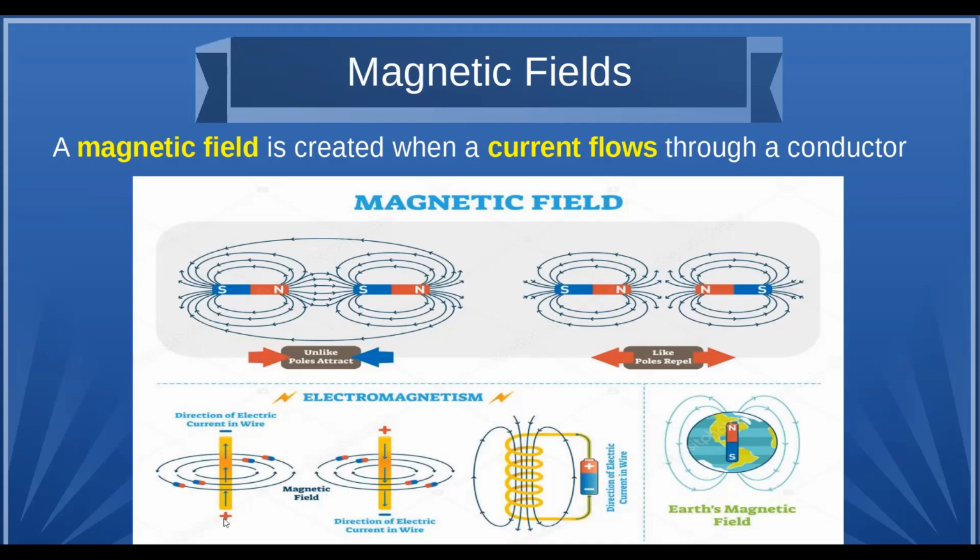So in this one, we're showing a conductor with the current going in that direction, and use the right-hand rule. Okay, your thumb is the direction of the current. Your fingers are the direction of the magnetic lines of force. That's kind of arbitrary, somebody decided at some point in time. So they're circulating in the counterclockwise direction if you were looking down from it. You have the opposite current over here, so they're going in the opposite direction.